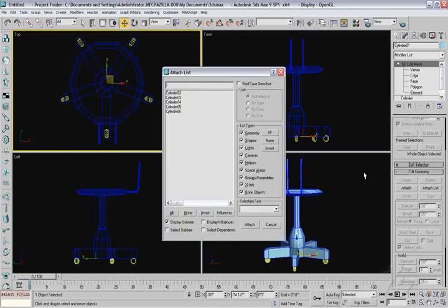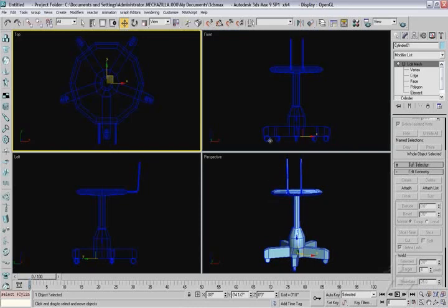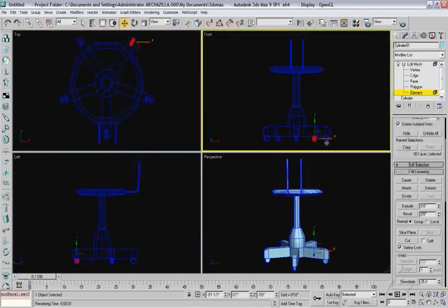If you click on Attach List, it will come up with all the other cylinders that are available, all of the wheels, and then we can select all of them and click on Attach. Now all of those objects become an element of the main object. So when you go into element mode, you can still select portions of this model, such as each wheel individually, and create a texture for it, but it is still considered part of the whole, such as office chair.